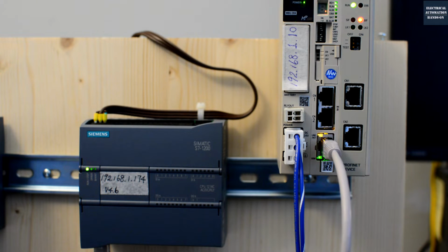Also on the Siemens side, to implement the Ethernet/IP slave, the adapter function, there's no cost either. We just need to download one library, one existing function block, and implement it in minutes. Then we can set up this communication. Okay, let's shift to the engineering platform and let me show how we can do this.